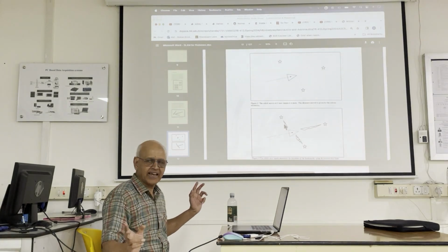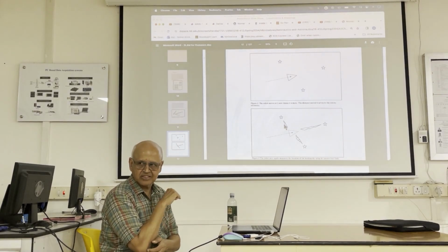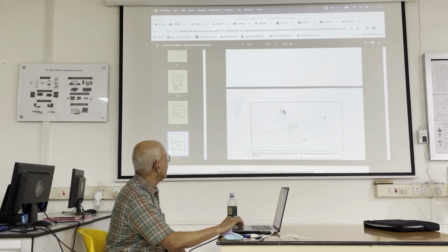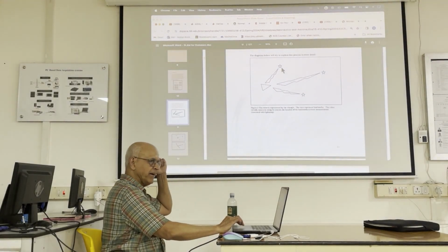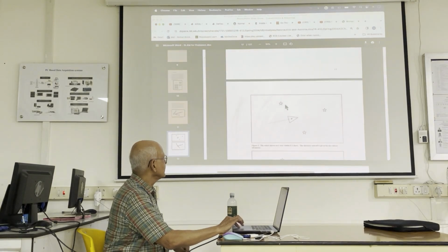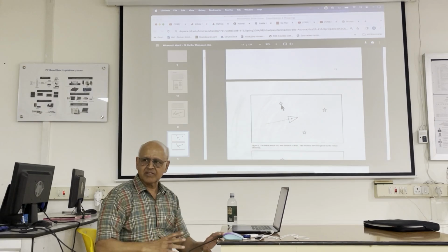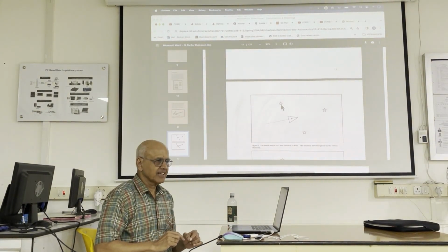So lightning bolts again. Now, there is a detail that is left out in this description. How do you know that this obstacle that you saw from back there is the same as this obstacle? Now, what if they are traffic barrels? They all look alike, right? So there is a technique known as scan matching.